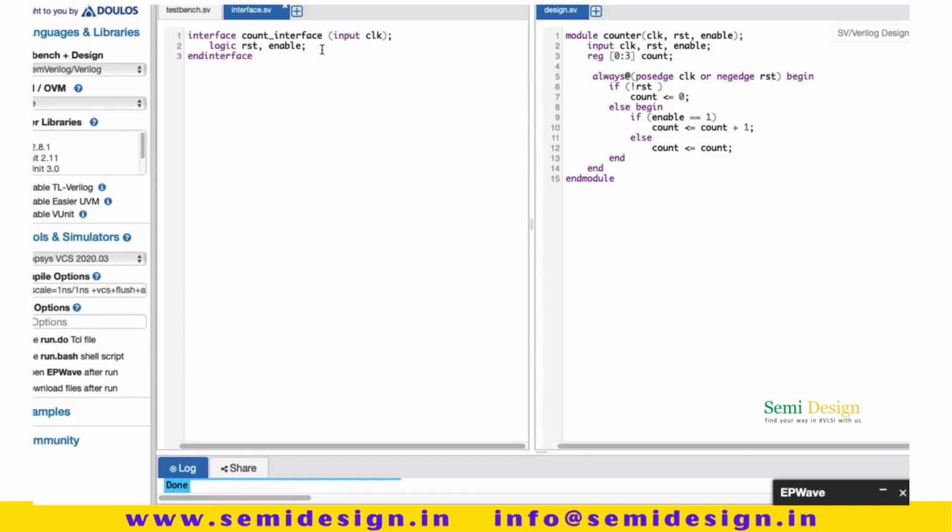We can declare directional information using the modport. It is used to indicate whether signals are going from design to testbench, or from testbench to design. We can also define timing information using the clocking block.